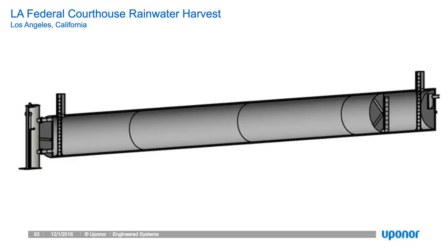And this is a more efficient design because the particular pumps for this project had about a 1.5-foot submergence depth, which is basically inactive hydraulic storage that can't be utilized. So we want to bring that outside the system to get the most storage inside the vessel as possible and minimize the footprint of the project.